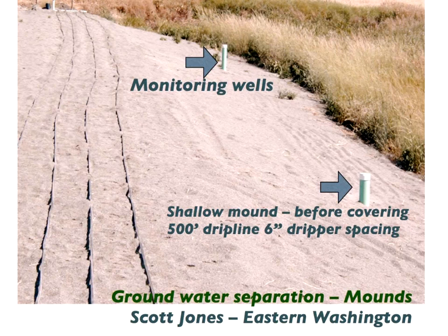The same argument could apply to a conventional mound. This is photographs taken before the covering soil was placed, sand was placed over the drip line. And these are 4 lines, 1, 2, 3, 4, and each 125 foot long. So very conveniently used a full 500 foot coil, and the drippers are only 6 inches apart.